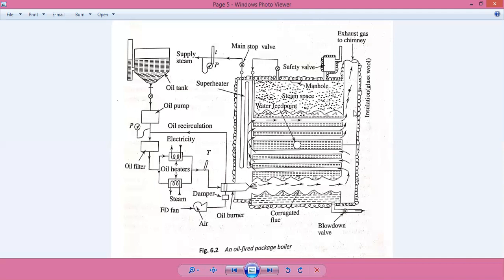There should be a safety valve always. It is spring operated, and the spring pressure is to be sufficient, not more or less, as required for releasing the high pressure steam which is beyond the capacity of the boiler drum itself. There should be provision to put out the fire. Holes should be formed somewhere for the entry of the operator, and for cleaning and rectification of any defects.